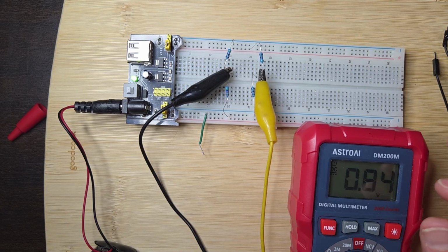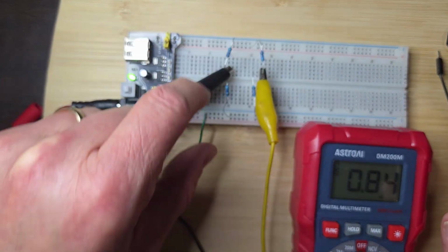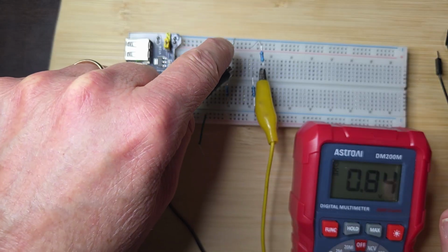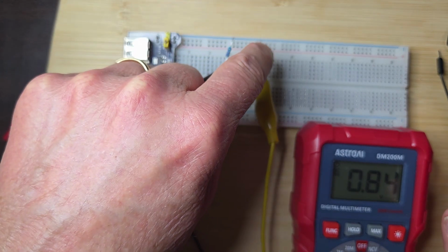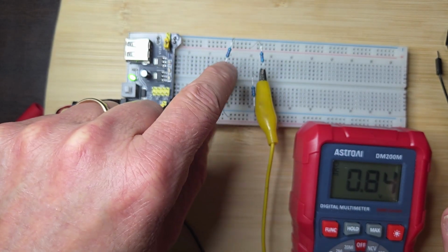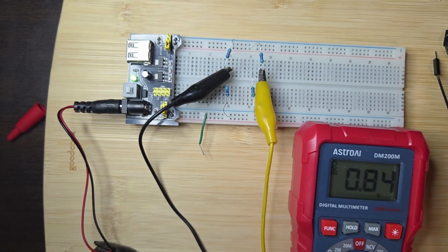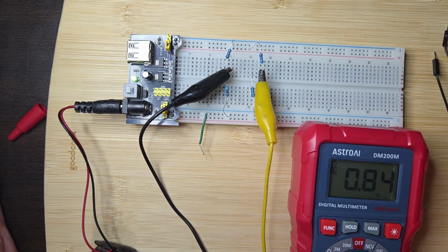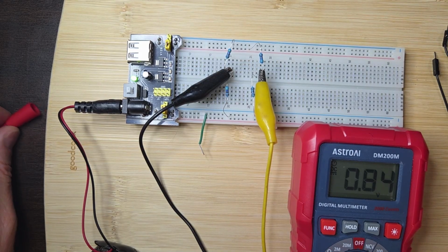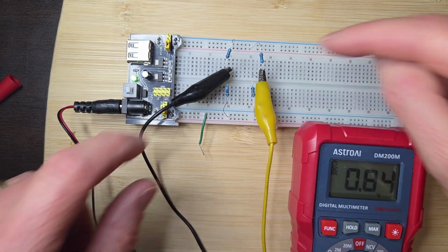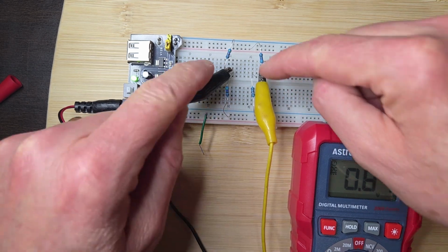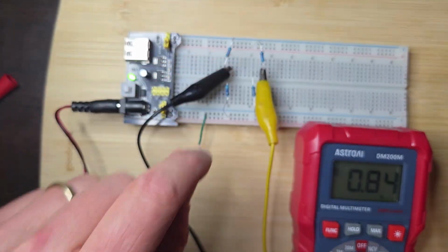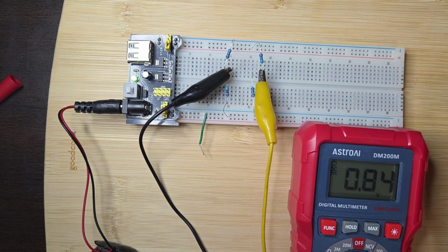The reason I have that is, it's close to 0, but these values are off a little bit. This one is not perfectly 4.7, and this one isn't perfectly 10k ohms. So if they're static and not changing, unless they had 0% tolerance, which I don't know of any resistor that does, it's going to be off a little bit. It's not bad though, but it's still off. It's not perfectly zero.